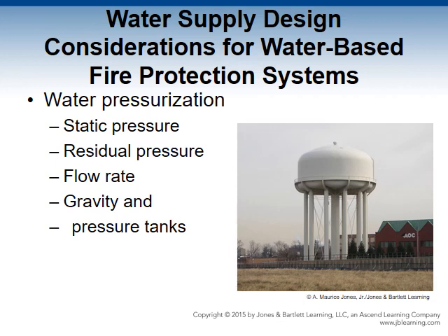Gravity and pressure tanks. A gravity tank or elevated tank is a freestanding tank that rises above the ground in a community or industrial area. They can serve the community water supply or just the fire protection needs in commercial or industrial settings. Tank capacity can be relatively small, such as 50,000 gallons, or very large, 500,000 gallons.